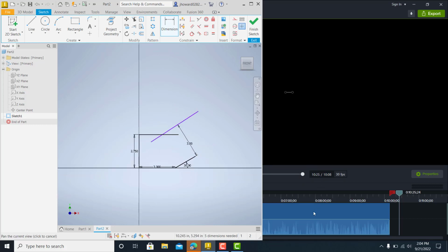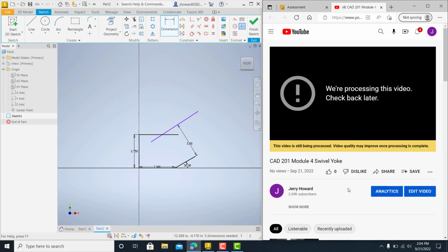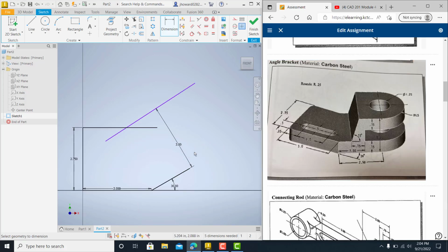Y'all see that? Get that back up there. So now with that on there, I can trim and clean this up over here on that side, as you see. And also 2.5, so I can click on this line here with dimension. And see how it's not doing that the way I want. I want that to be in the line dimension. So I grab it, and if I right click, I can go in here and hit aligned. And it gets it lined up for me.